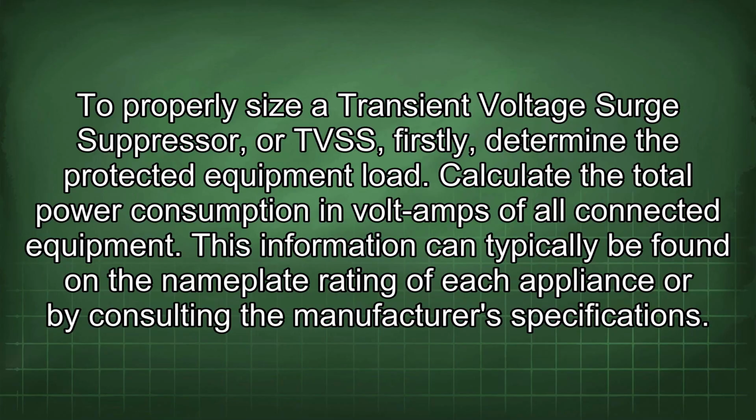Properly size a transient voltage surge suppressor, or TVSS. Firstly, determine the protected equipment load. Calculate the total power consumption in volt-amps of all connected equipment. This information can typically be found in the nameplate rating of each appliance or by consulting the manufacturer's specifications.